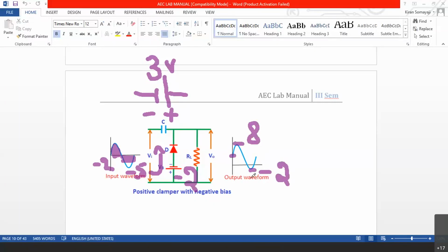This way, now the signal has not remained pure DC. You can see the signal is in the first quadrant also, it is in the fourth quadrant also. So the signal is not pure DC, it is now AC also, partly it is AC. That is the wonder of these clamper circuits. In the earlier two circuits, it had become completely DC. Now here it has not become DC, partly it has remained AC. But still the signal got shifted up by